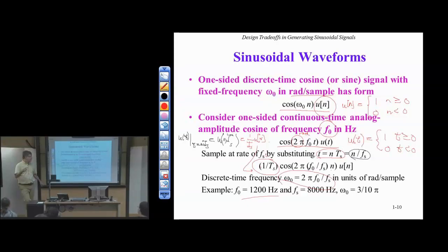So you could map the 1 in the floating point domain to 32,767 as a 16-bit int. And you would do that by setting the gain to be 32,767. That's pretty extreme. You don't have to go extreme. Maybe 30,000 is enough. Maybe 25,000 is enough. But leaving the gain at 1 isn't going to look all that great as a cosine waveform on your oscilloscope. All right, so we're going to let the gain be flexible, and we're going to change it as we need to change it.